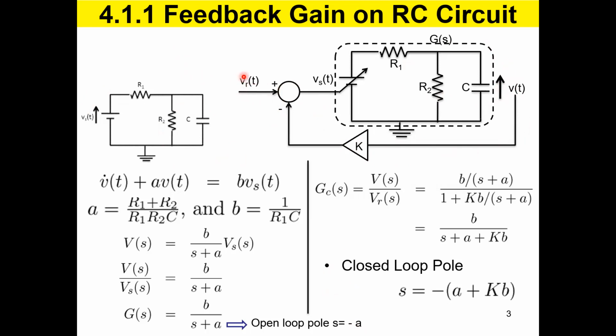I want the voltage to be at this level, whatever, right? Not what the system naturally gives out, but I want it to give me this level. And if there's any change between these two, you generate a difference and you use that one to drive this voltage. So now this one is not a constant. Now you're going to change it based on this difference.